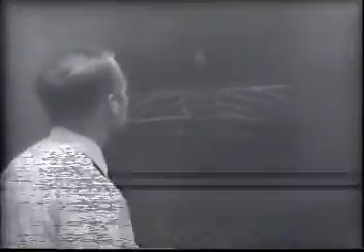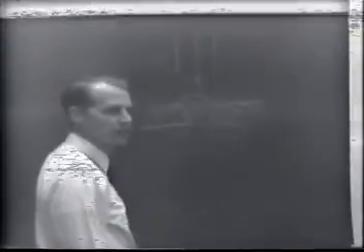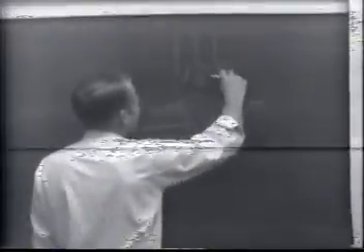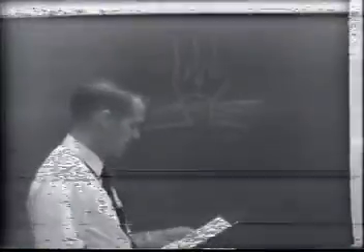And in moving in this direction, the third way that we will lengthen the arc is to introduce obstacles in the arc path. If we get these conductors farther apart and introduce some insulating materials into this arc path, which is going in a direction like that, the arc is going to tend to follow the surface of that path there. And this again would be another thing that's going to lengthen the path. It's going to increase the arc resistance.